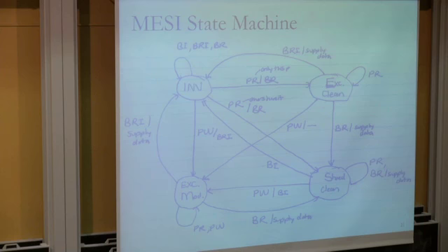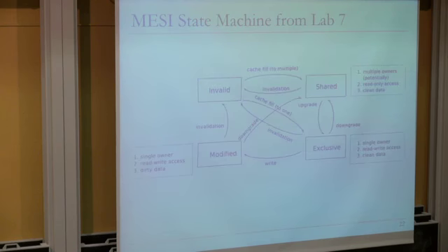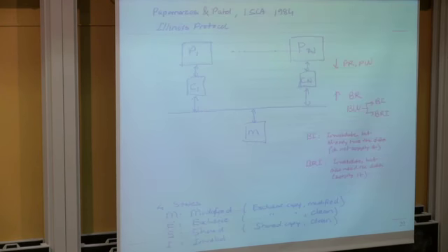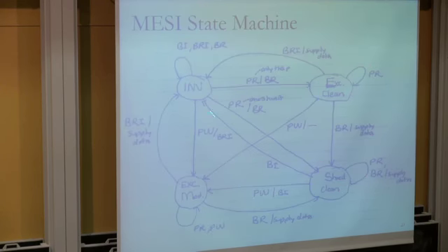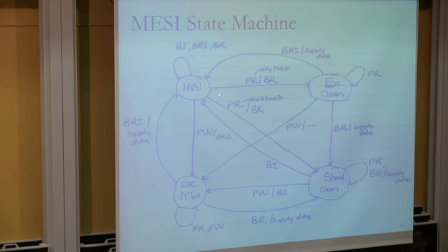So this state diagram, which I will not go through, but you can study on your own, I will go through the Pentium Pro state diagram a little bit, which I rushed through last time. But the state diagram is complete in the sense that it tells you what happens. Actually, maybe I will go through this part. So this is the state that I was talking about. When you get a processor read to a cache block, you can go into either the exclusive clean state, this is the E state, or you can go to the shared clean state.